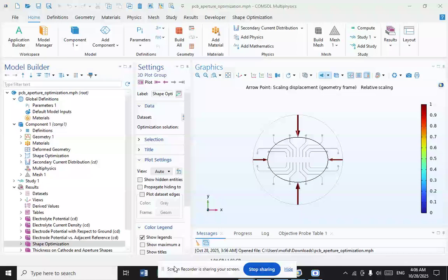And throwing power is an important parameter that provides a measure of the uniformity of electroplating current and consequently the uniformity of the electroplated metal thickness on regions of the part that are near to the anode compared to regions that are far from it. It depends mostly on the composition and temperature of the electroplating solution as well as on the operating current density. A higher throwing power of a plating bath results in a more uniform coating.